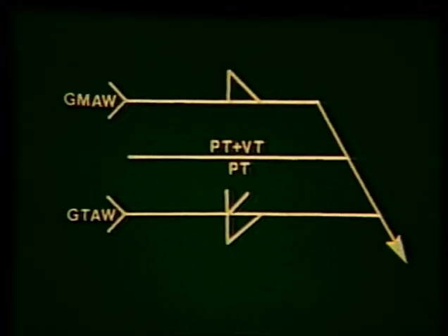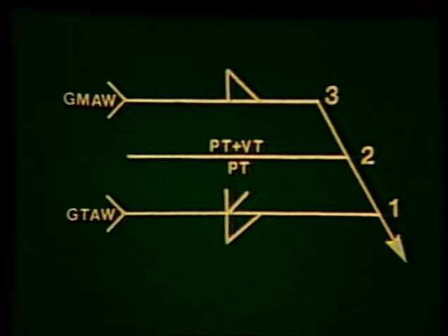Non-destructive test symbols can be combined with welding or other test symbols with the use of multiple reference lines. The order in which the operations or tests are performed is indicated by the order of the lines, the first operation being closest to the arrow, and the last farthest from the arrow.